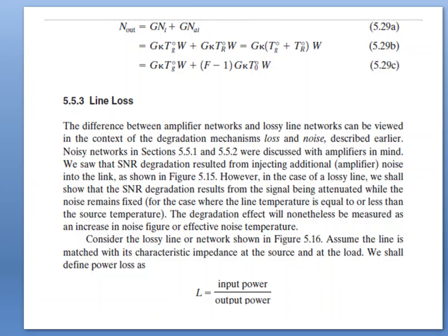For a purely resistive termination, Tr is never less than the ambient temperature unless it is cooled. It is important to note that for reactive terminations such as uncooled parametric amplifiers or other low loss devices, Tr can be much less than 290 Kelvin, even though the ambient temperature is high.